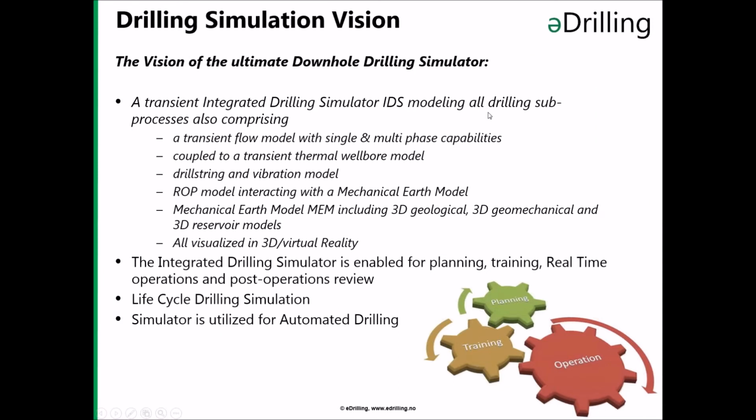The ultimate vision for drilling simulation, I have, for myself at least, written down here. This is to have a transient integrated drilling simulator which models all the important drilling sub-processes, which also comprise transient flow modeling with single and multi-phase capabilities, coupled to a transient wellbore thermal model, have drill string and vibrational models, ROP models interacting with mechanical earth properties, and also a mechanical earth model including 3D geological, geomechanical and reservoir models. All these visualized in a 3D virtual reality environment.